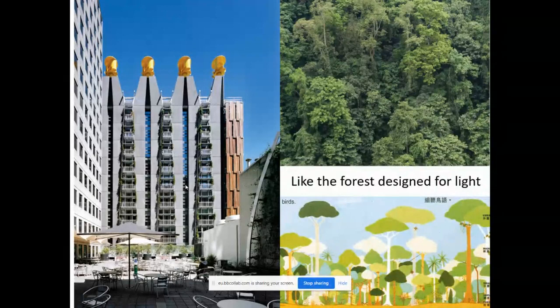Now the ducts on the north side are dark color, and that's another thing. Albedo, which is the reflectivity of color, is very important if you're worrying about energy. So black ducts, or dark ducts, help to pull the air up.